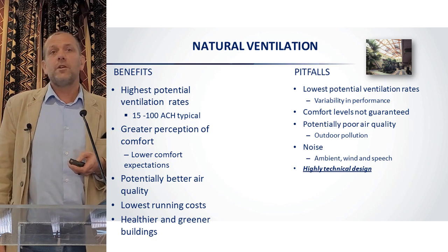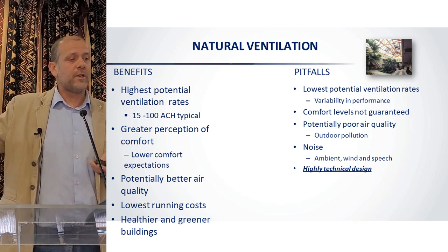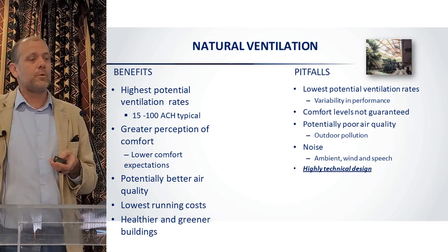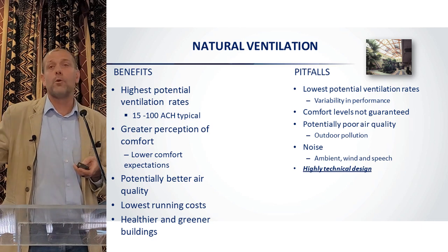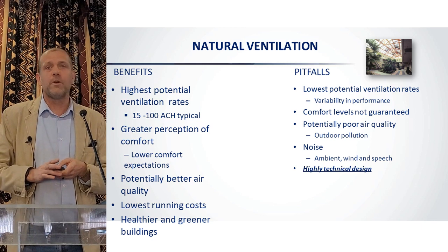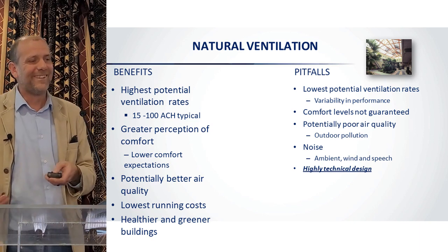We tout natural ventilation a lot. It has a lot of benefits. It's the highest potential ventilation rate. 15 to 100 air changes per hour is typical. You have a greater perception of comfort with lower comfort expectations. It's a bit of a strange phenomenon. People are more comfortable in naturally ventilated spaces because they don't expect to be as comfortable.